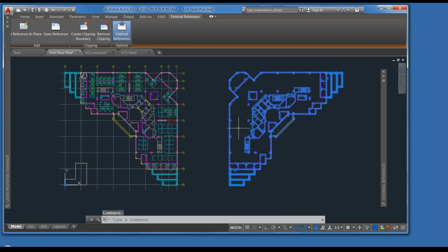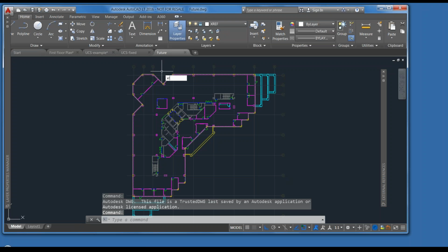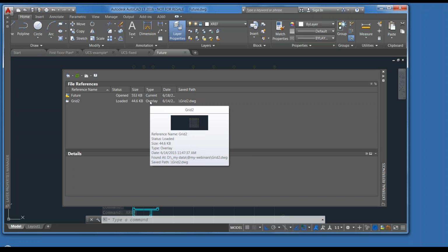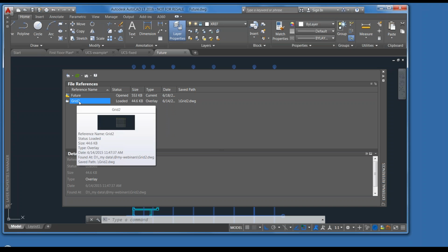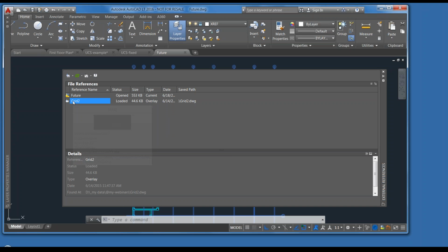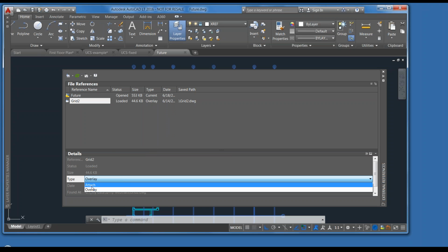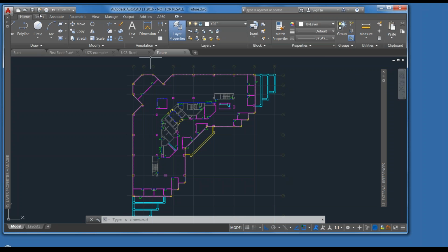this drawing. So I'm going to go ahead and just open this drawing directly, go to X reference, because I see the grid there, and sure enough, it's an overlay type, so it's not going to carry through when I pull it in as a reference into another drawing. And remember, we can change the insertion type directly from this palette by highlighting the X reference. We can come down here, this is a pull down, and you can switch it to attach. Make sure to save the drawing.